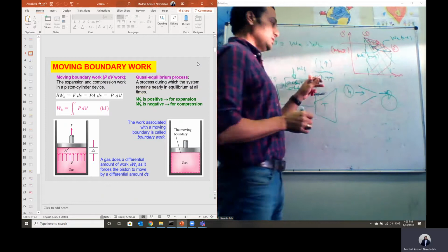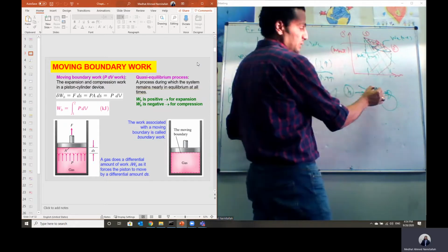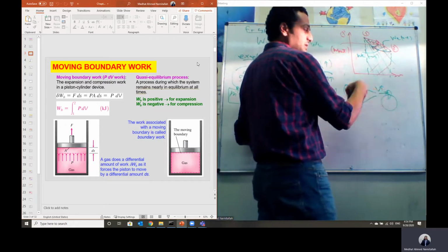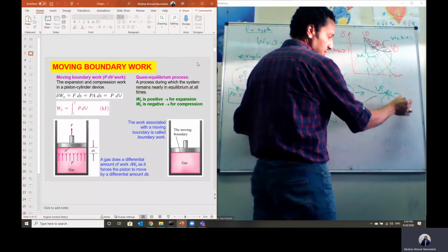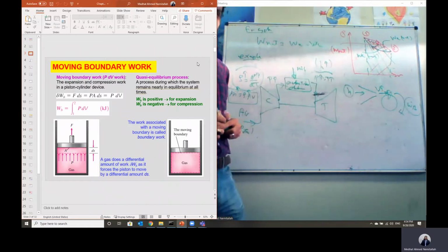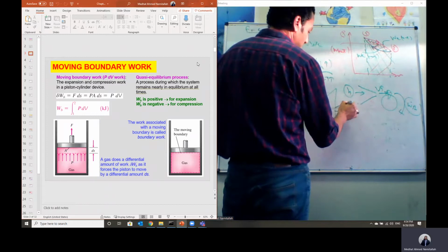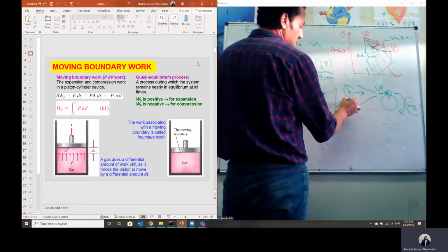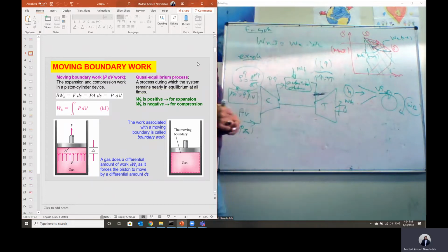enthalpy, or high flow energy, would be converted to kinetic energy, and this kinetic energy of the hot gases will hit the bucket. Then in this case we can generate shaft power out of this turbine. So the shaft of this turbine will be moving in this case, and we will generate shaft power.